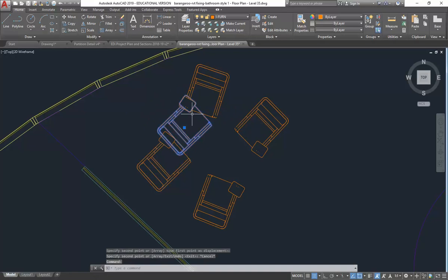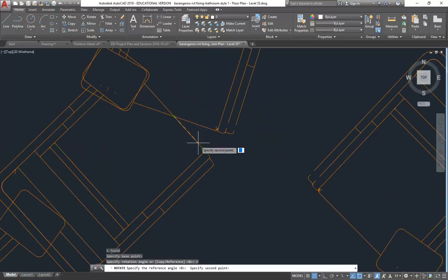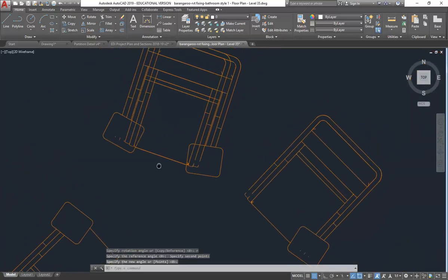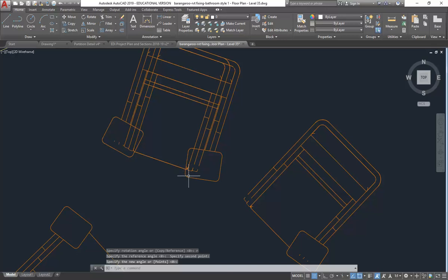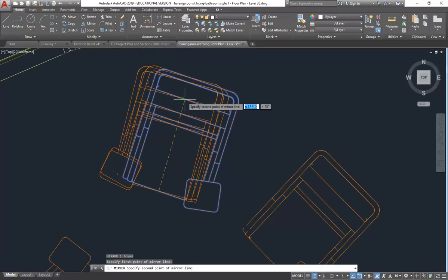You can switch the blocks over in another way, but that's probably even harder, so this is probably the easiest way. So yeah, it's pretty good. Most of the time it will manage the blocks for you when they come from Revit, but not always. And it's because they're mirrored. So I'd have to manually fix that myself, but it's still easier than doing it all again.